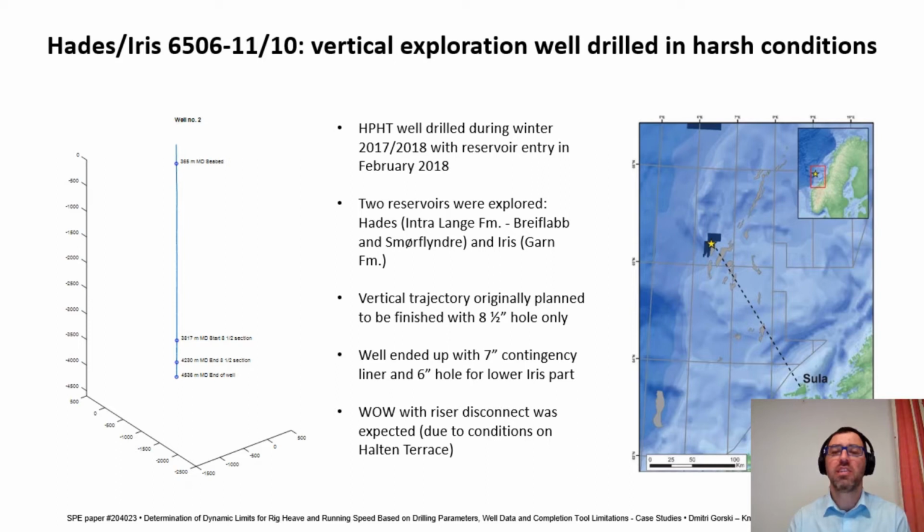As a part of operations planning and to get a more fundamental understanding of heave impact on the well design, OMV did a study with a Norwegian research institute up front before drilling the well. This study presented a set of maximum variations in downhole pressure, peak-to-peak values, for various heave amplitudes and heave periods with specific BHAs at specific depths in slips, and the string is not heave compensated. Such a study is a valid way to get a pre-drilling indication about what heave is doing to your wellbore pressures at critical depths. This was all done pre-drilling in order to assess the possible impact of heave on our wellbore pressures.